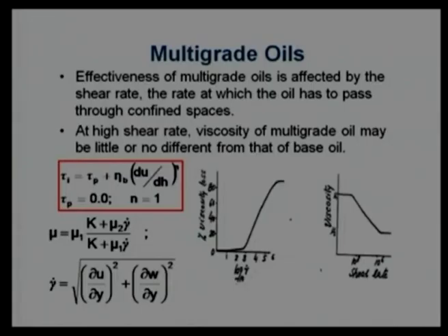What we have considered previously in examples, mostly we assume that the relative velocity or sliding velocity is only in one direction, that was the x direction, that is why the velocity was expressed by u. However, for general application, when velocity is in the x direction as well as the z direction, then the shear rate in y direction can be expressed by the first term, and then the shear rate in the second or z direction can be expressed by the second term.